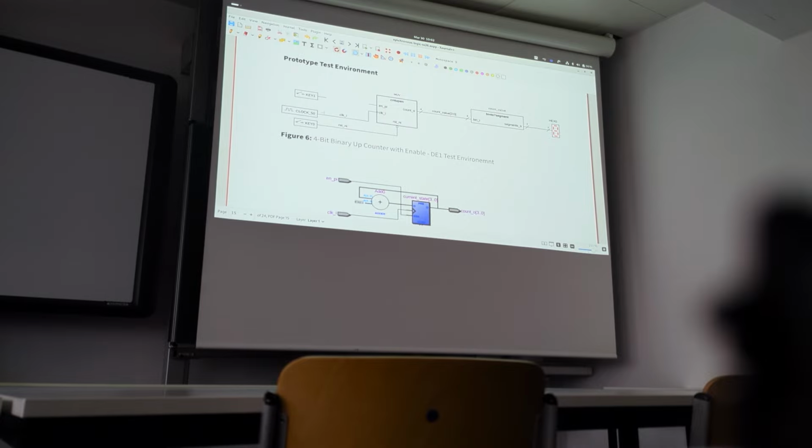We connect the clock input to the clock oscillator, which is directly on board. We connect one of the keys to the asynchronous reset so that we could press an asynchronous reset. And of course, we can also use another key for the enable input to switch enable on and off and check that. So what is actually missing here is the output connection.